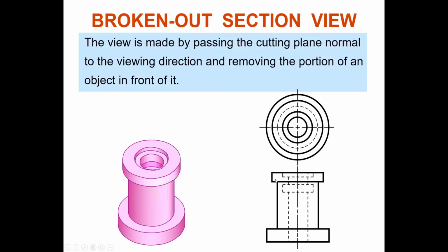You straight away think, sketch first on paper, what is the hidden section view on your front view. Okay. Alright, so this is typical orthographic, but this one you can do full section. This one, you do half. This one is not offset sectioning, guys. No offset. This kind, you can do full section. You can do half section too, like I explained before. Also can do, but you can also do this type of sectioning.